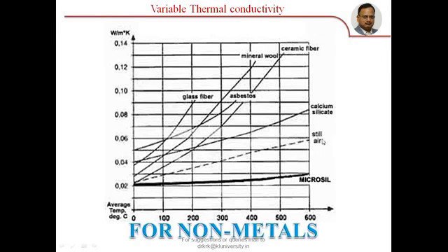But carefully follow, if the air molecules are in motion, they start convecting heat. The convective transfer coefficient is again in the order of 10 to 50 watts per meter square Kelvin. So it may again affect the heat transfer. So when you have still air, like entrapped air, either between two window panes or when you join two different materials like thermal contact resistance, this still air acts as an insulator.